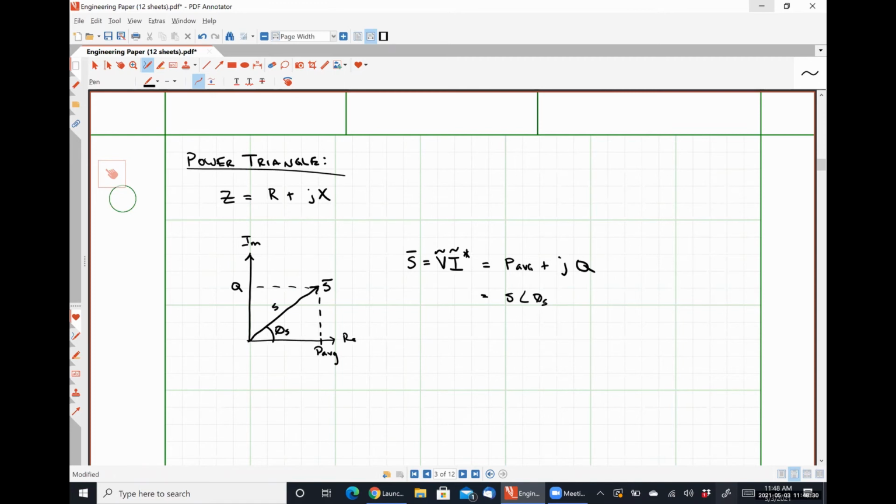So for me personally, whenever I am analyzing a steady state sinusoidal circuit for any power quantity, I don't care whether I'm asked for average power or reactive power or anything like that. I calculate the complex power and then use that to get the quantity that I want. Because that way I only have to remember one simple equation, which is just multiplying two numbers together to be able to get literally every quantity that I could ever care about, okay?